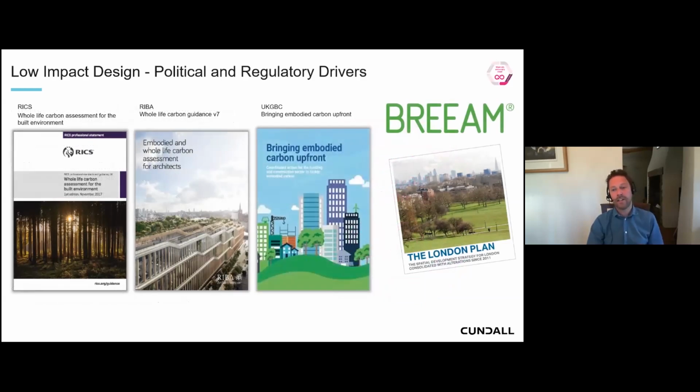I think historically there was very little driver on this. There was a lot of driver on operational carbon, but we're seeing that change. RICS, RIBA and UKGBC have now produced quite extensive guidance on that. BREEAM has a far greater emphasis on embodied carbon going forwards, and the London Plan and other plans around the world are starting to bring this into focus as well. Again, they're calling for a whole life cycle, which is not only operational, but embodied as well.